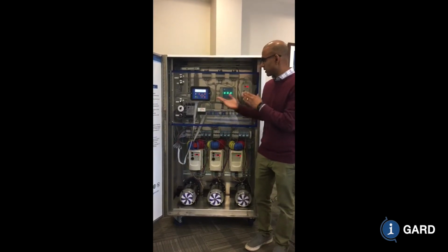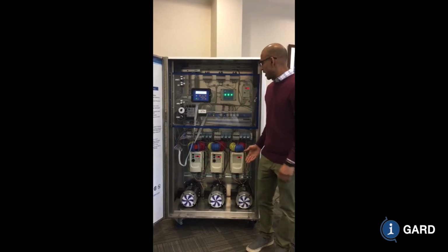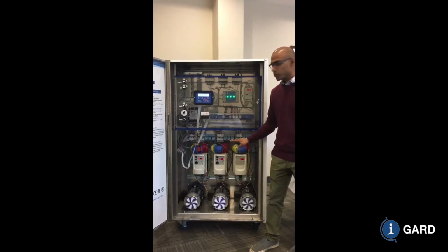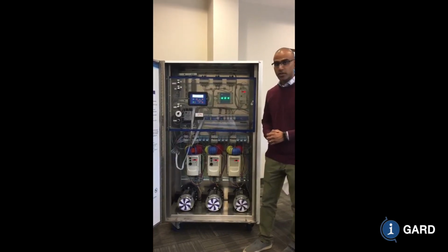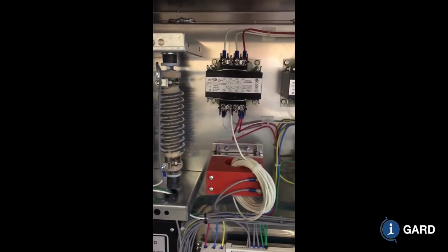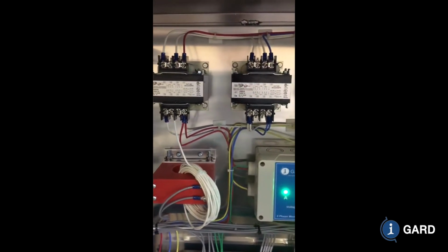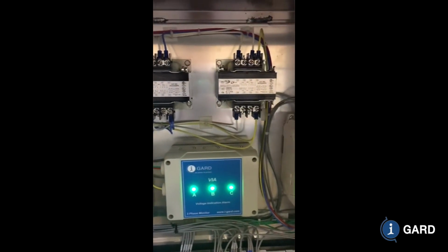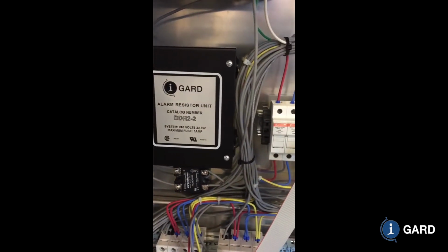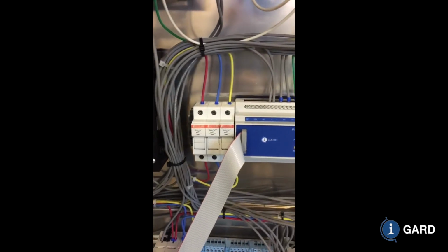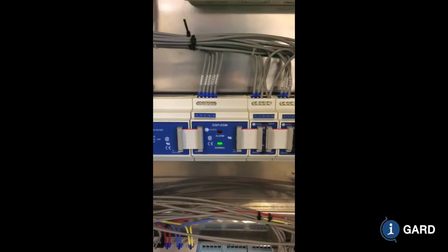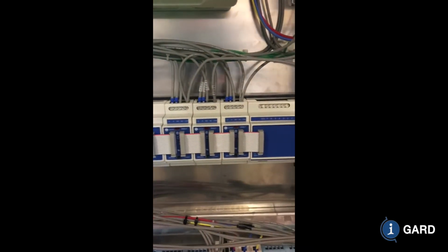So we have our DSP system connected to it, and we're monitoring both the system for its voltages to indicate a ground fault, as well as the fault current for each feeder. One thing about a high resistance grounded system is that when you have a fault, you can run continuously when a fault is present, and you see that voltage displacement. So we're going to have a look at creating a ground fault and showing what the system looks like.